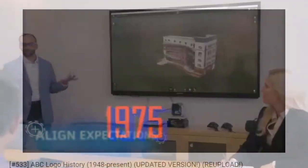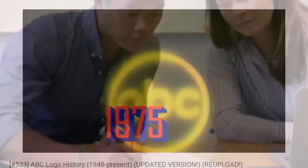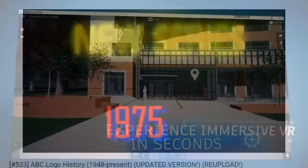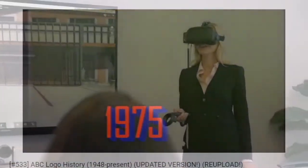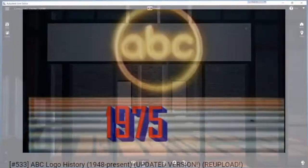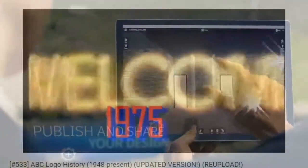For quantity reporting and scheduling, materials that are applied with the paint tool are distinguishable from those that are used as the body material of host object elements. To remove paint from an element, use the Remove Paint tool. Now that's an important aspect of it, not just in the aesthetic appearance of the wall, but in the reporting of the amount of surface material you painted on it, which is indispensable.